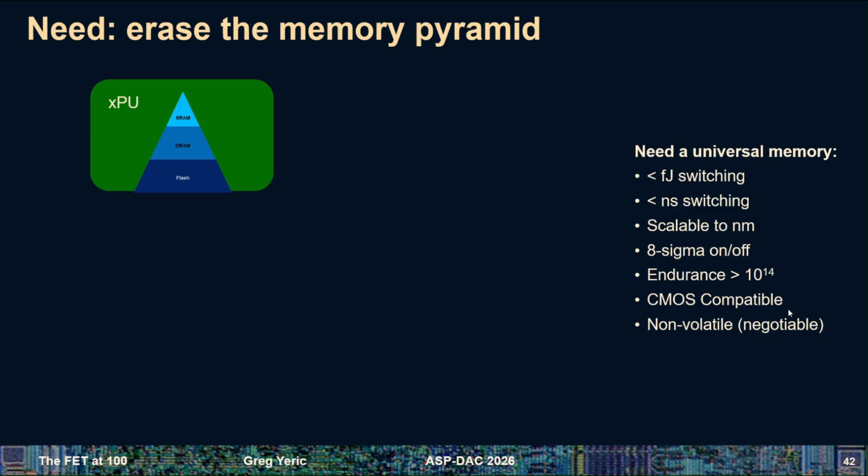So we've got a transistor on a wafer, and we want to put a new type of memory, call it a resistive RAM, which is a class we'll talk about. You might want a 1500 degree C anneal to make the crystal recrystallize after you deposit it. But after you put wires down on the CMOS logic, those wires really can't tolerate anything over 400 degrees C. So you have a 400 degree C cap on anything you want to process on the wafer, and then other things like impurities.